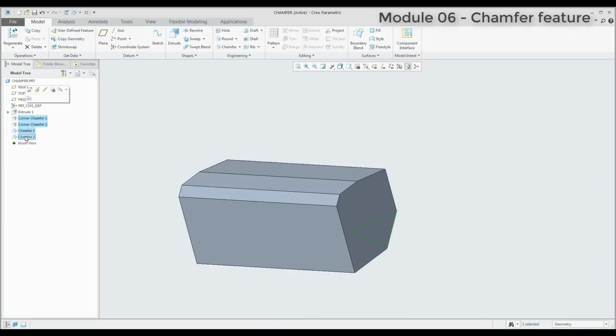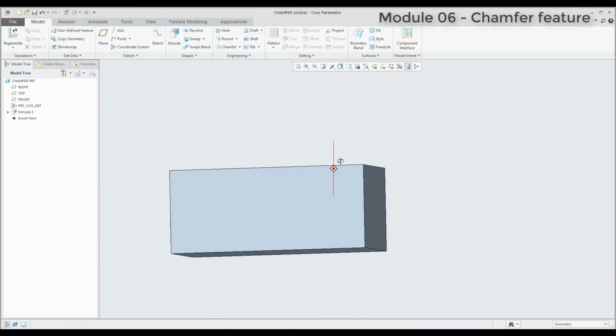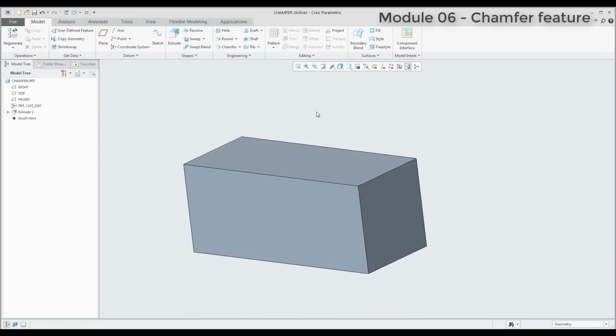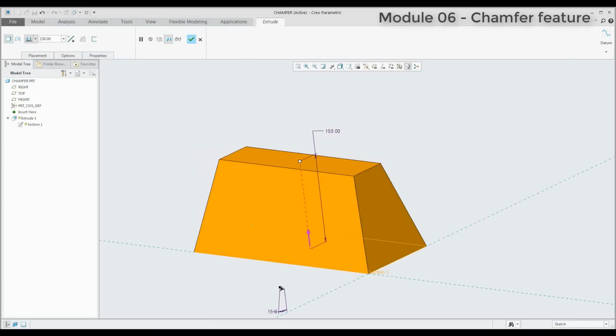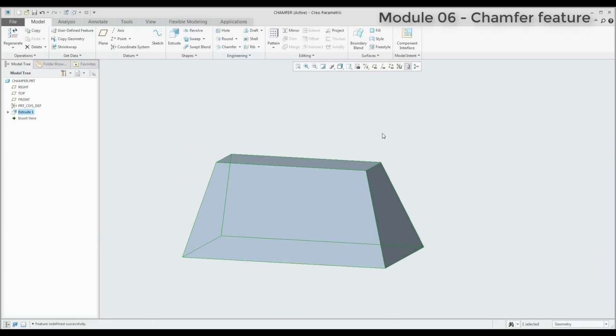Okay, I don't want to see this information, so I will delete it, and I'd like to start from a different shape. You know that it's possible to select the definition for the extrude feature, and over there is the function add taper, and I'd like to specify the taper. On this example, I'd like to explain to you what it means O per O. Again, you can select the icon from the menu, or you can select the edge and the icon from the layout menu. It's up to you what you want to use.